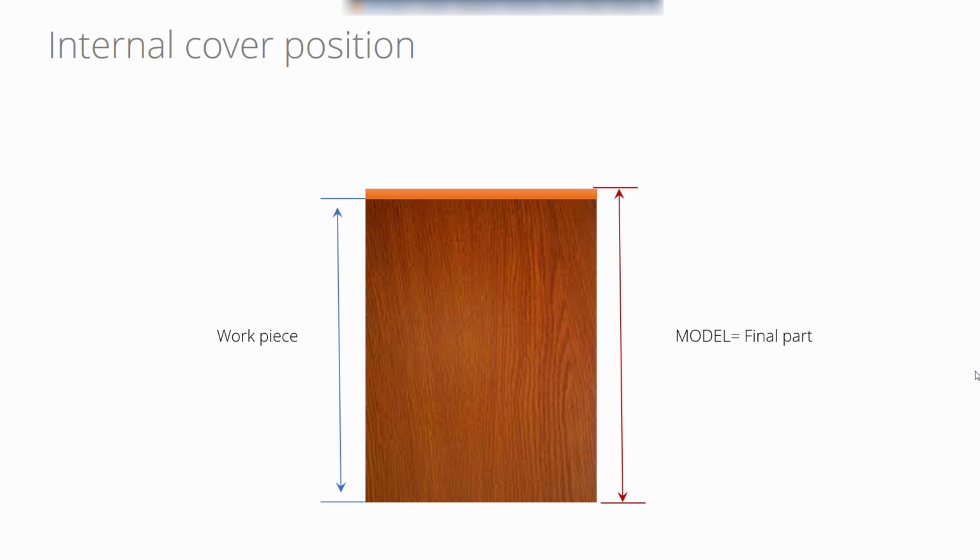Also, you can adjust the oversizes for the technological purposes. You can change the grain direction, which also affects the workpiece size, and all of that is made automatically. So for you it's important to make the model correctly. If the model is designed correctly in Woodwork for Inventor, all the information will be adjusted automatically in the right way.